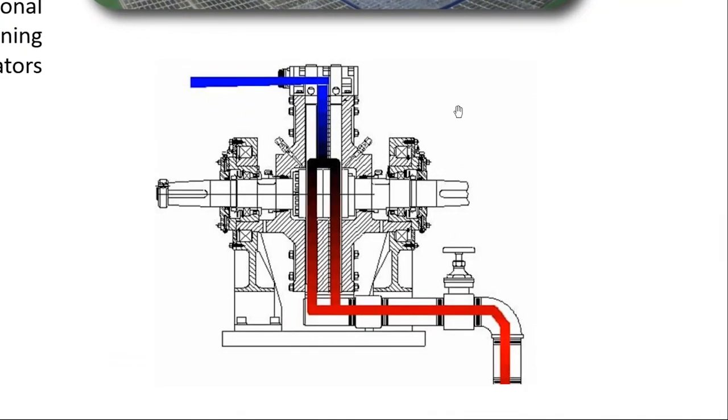A dyno is basically rotors and stators, and what's happening is we're introducing water into the top of the dyno. Meanwhile, as I think everybody is aware, this is the shaft, and the shaft is rotating at the speed of the engine. These two devices, you can see here, it's white and then it's turning into red. These are the rotors in the dyno, and those are spinning. Meanwhile, the stators, which are the plates on either side of this two-rotor dyno, are stationary.